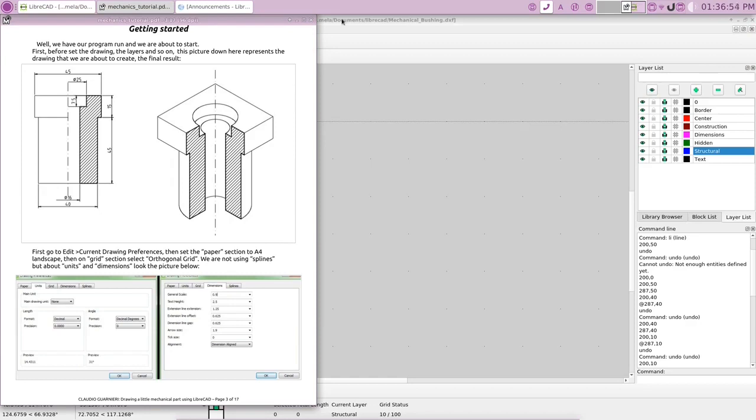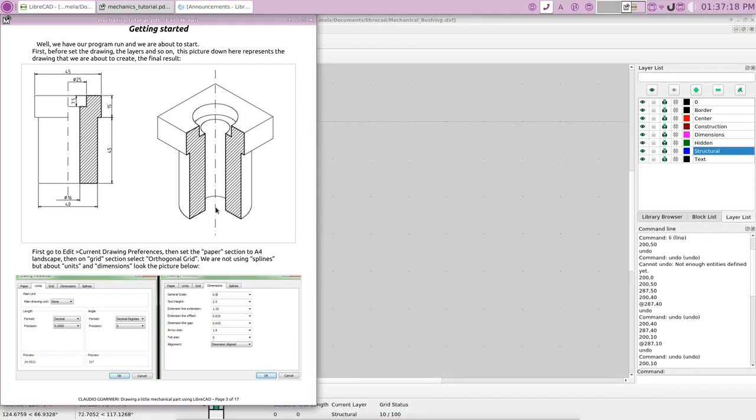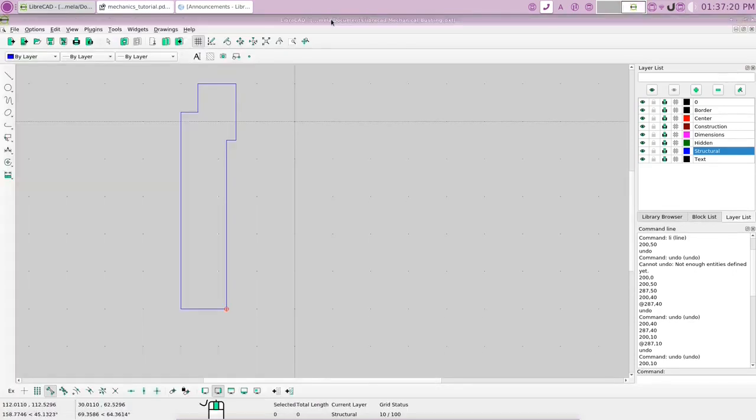So what we can do here is, this is the diameter of 25, and this inner one is a diameter of 16 units. But the center line would be half, would be a radius. So the radius is 12.5 from this edge to this line. And the radius here is 8, half of 16 over to the line. Okay? So let's do that to find the center line.